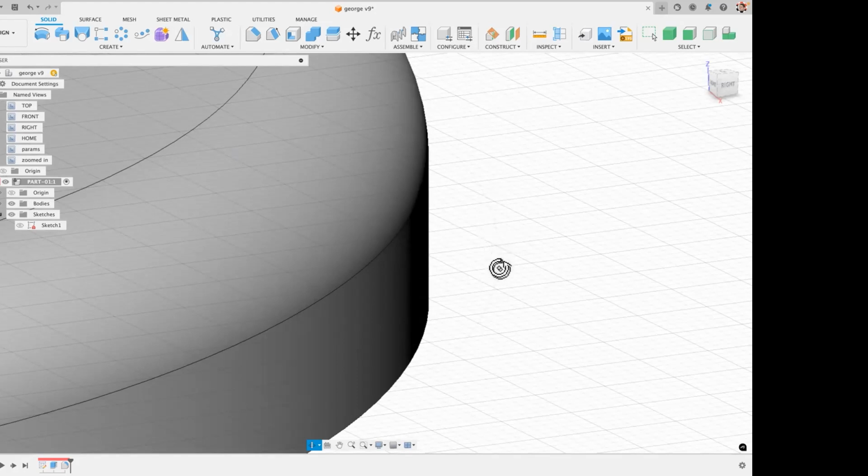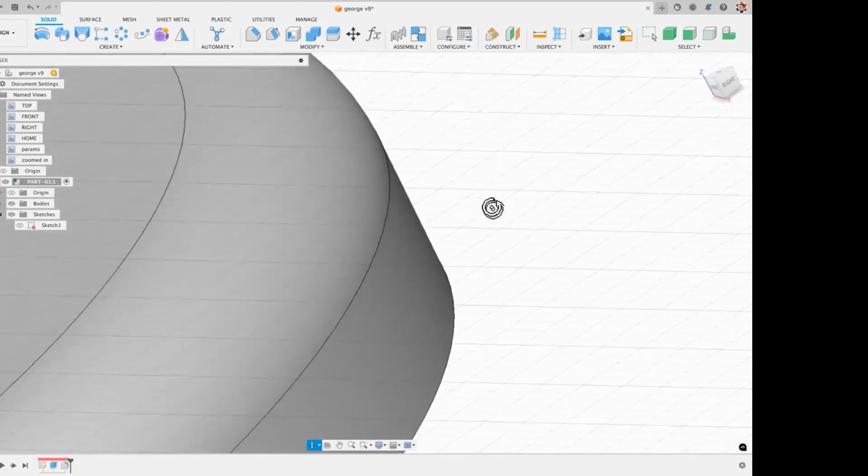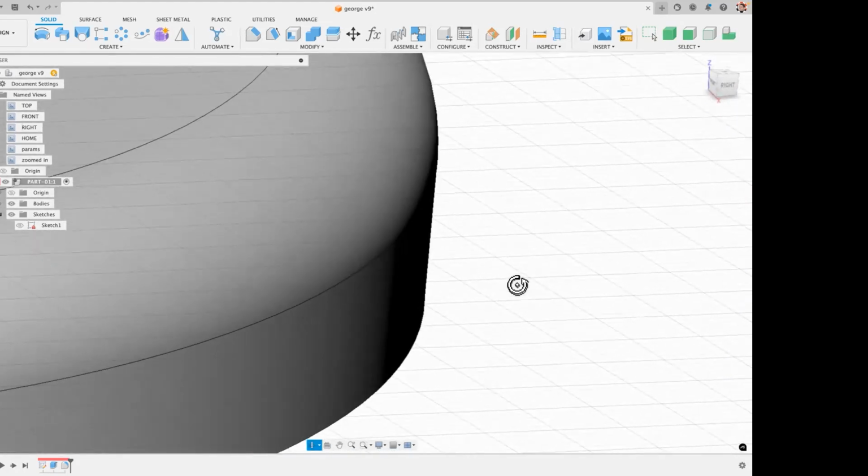If you get to 3 o'clock or 9 o'clock, you get yet a different icon. Okay. If you're at 3 o'clock or 9 o'clock, you just have one circle and it's going to orbit around that plane. Okay. If you're at 12 o'clock or 6 o'clock, it's going to be the vertical plane and it's going to do it this way. Okay. If you're on the circle but not on one of those cardinal four, it's going to roll down the way you're looking.